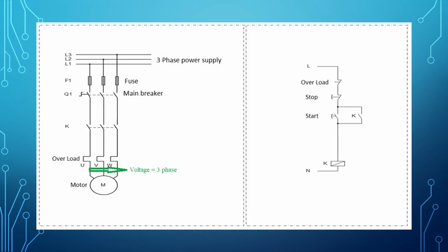It will be more efficient if the motor terminals are dismantled, and the voltage is measured from the motor starter output cable. If the cable terminal's voltage is matching the supply voltage, then the motor is defective.